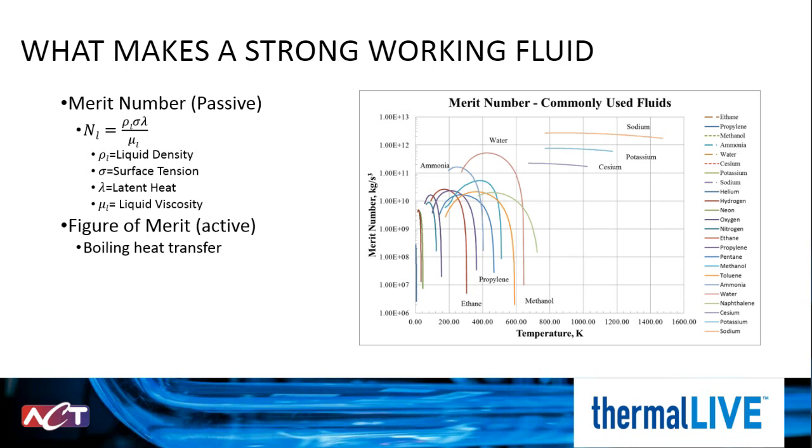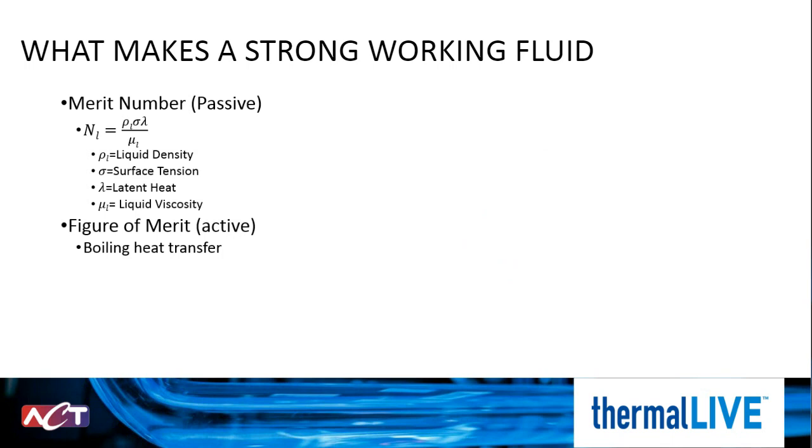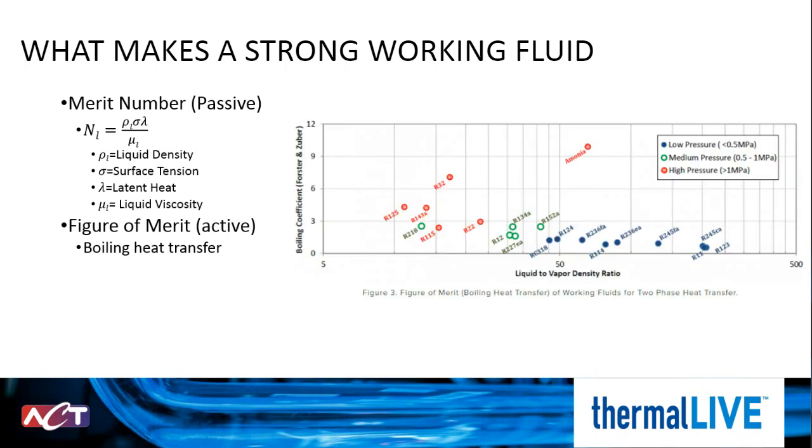For an active two-phase solution, we look at the figure of merit. The chart on the right shows working fluids with high figures of merit, or high boiling coefficients and liquid-vapor density ratios. You can see many refrigerants listed on this chart.